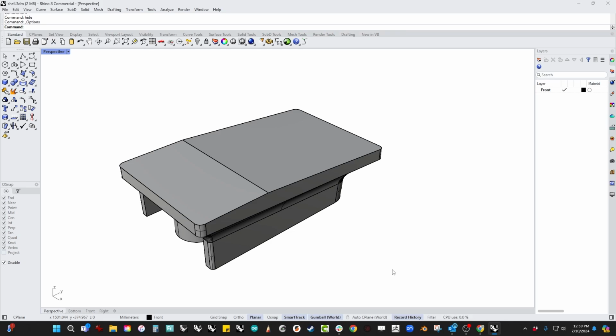In SolidWorks, I don't know what the tolerance is, but it's like 5 decimal places. You need to talk to whoever is going to work on this part after you, find out what their working tolerances are, set up your file before you draw the first line to have the same tolerance, and then work at that tolerance, okay? So I just want to get that out of the way. But in this case, let's just assume that we're handling this all the way.